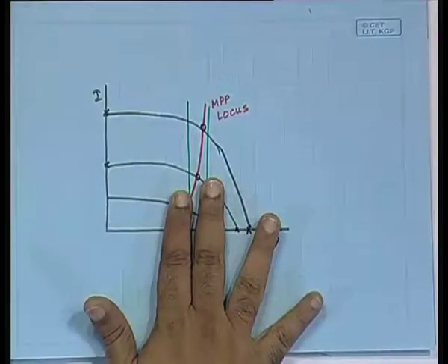That is what many people do not understand. They simply take a battery and connect to the photovoltaic panel. After all, the specification says that it produces 24 volts and I have got a 24 volt battery, just connect them. Very bad way of doing it, because there has to be some kind of a matching between this thing and that thing, and that is what any energy engineer should know properly. You cannot simply connect any battery to any panel. You first have to measure the characteristic of the panel at various levels of insulation, look at the trajectory of the maximum power point, and then identify the range in which it will work close to the maximum power point, and then choose the battery whose range of oscillation, change, variation of the voltage is within that range.